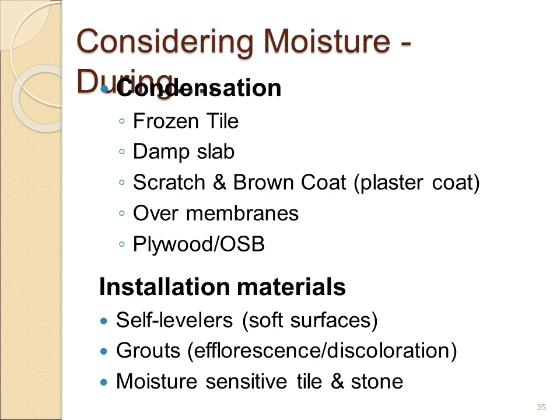So some people will plastic off an area, and we had one area that was entirely plastic off, and the temperature was very high, the humidity was very high, and there was condensation on the surface of the leveler, because the levelers incorporate a lot of water in their mixture, and the surface became very, very soft because it couldn't cure out because of the dew point and the amount of moisture on the surface of the leveler. So although you want to protect your levelers from a strong wind, you do have to have air, and you have to let that humidity get out somehow.